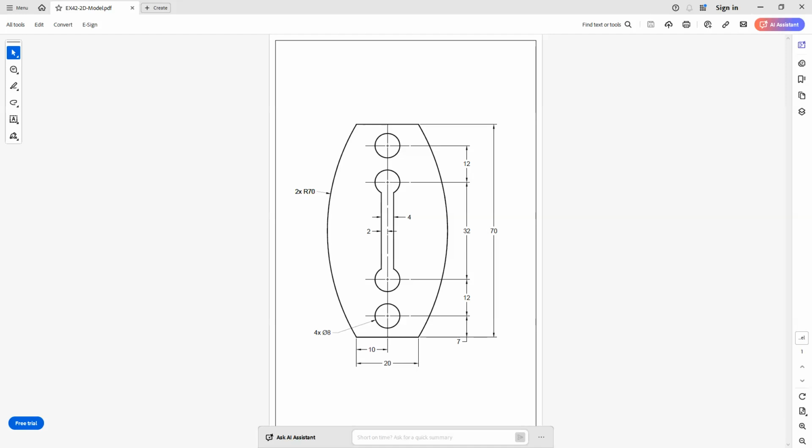So if I create my circle at this location, and that's what I'm going to do in the drawing here, I will copy this circle going up a distance of 7. And then I'm just going to type in the next number here, which is going to be the 7 plus the 12, which should give me 19. And then we would do a little bit more adding here. And the next one should be 51. And hopefully my math is correct here today.